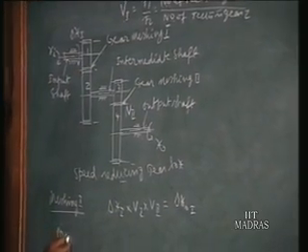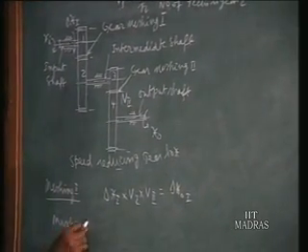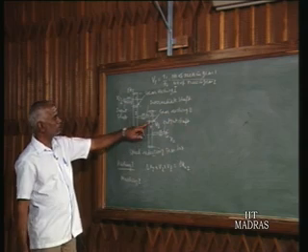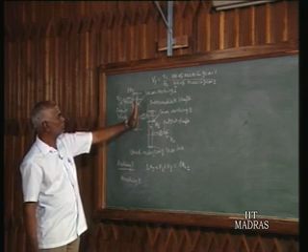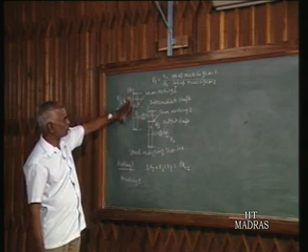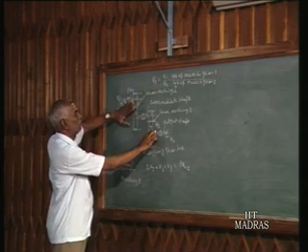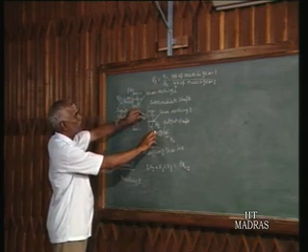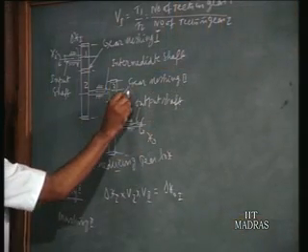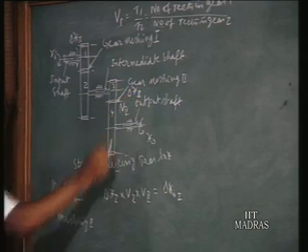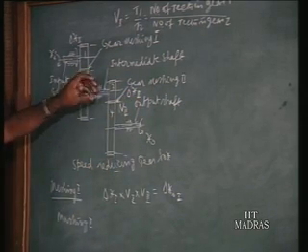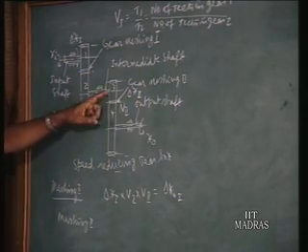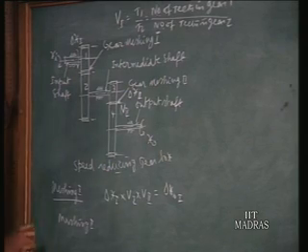Similarly, consider gear machine 2. We are considering this gear machine and assume this shaft does not exist at all, and hold this gear 4, and you will have, due to backlash, a small rotation of delta x2, plus or minus delta x2 at the gear 3 or pinion 3.